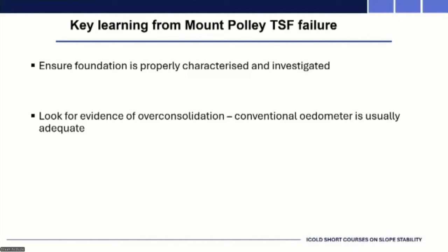If we start applying traditional soil mechanics, we can often get ourselves into problems. Transported soils go through the process I've just talked about: deposition, accumulation of load, perhaps removal to give you overconsolidation, hence a pre-consolidation pressure. Residual soils, weathered in situ, have no stress history in the same way.